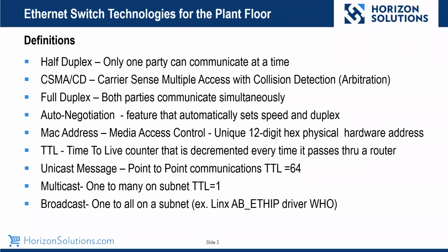Because the first thing I'm going to talk about is how we can break a network. So the first way we could break our network is this protocol called auto negotiation. So by default, all of our products, and pretty much all products, come with the configuration of auto negotiation. So the thing is, some people decide that they're going to hard code their nodes or their switches. So say you have a PLC and you say, I really want this node to go through, so I'm going to set this thing 100 meg full duplex. So I set my PLC at 100 meg full duplex. But on my switch end, I leave it for auto negotiate. So what happens when that auto negotiation goes out to that PLC, it says, I can't auto-negotiate that.